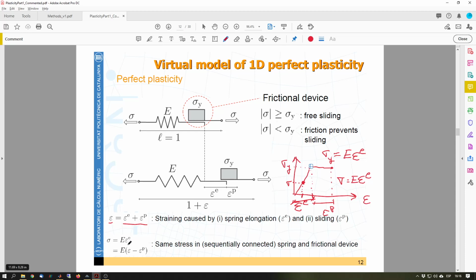So this is going to be my constitutive law. The important bit is that my constitutive law is still valid, but I have to take into account only the elastic strains. With respect to what I see, my total deformations, I must then subtract from the total the plastic strains. This is the main notion for the whole of plasticity. I have these permanent or remaining or irreversible strains that must be discounted in order to give stresses proportional to the Young modulus.